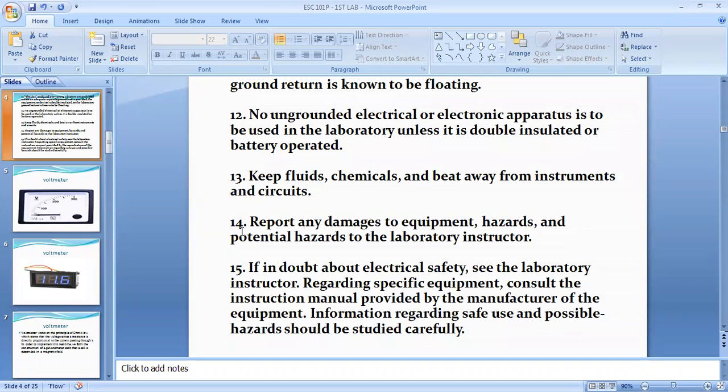First, you go and turn off the power supply. That is the first thing you will do. You turn off the switch, you turn off the main switch of the house, you turn off the main MCB of the lab, so that you cut the power supply. That is the first thing you will do.